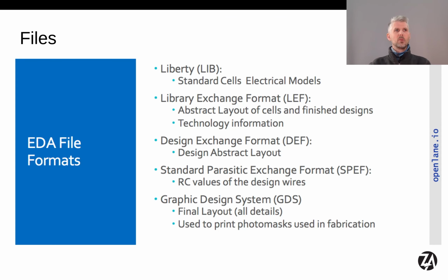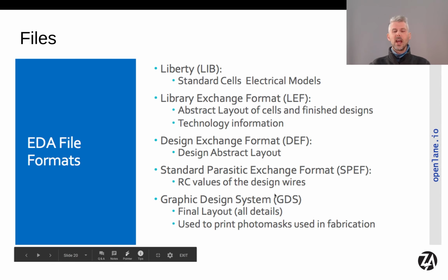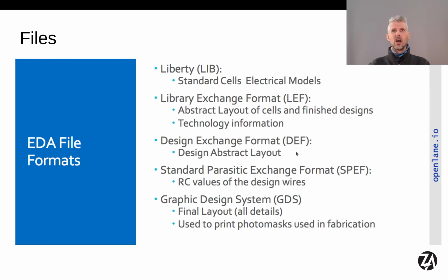So a quick note about files. The most important ones are the GDS files. Those are the ones that we end up generating and sending to the factory. And then we'll be working a bit with DEF and LEF files. So once you have millions of cells in your design, loading up all of them and all their internal detail is a real struggle for your computer, even if it's a powerful one. So we have this abstracted view, and that's a DEF file. So you'll get where things are and where the inputs and outputs are, but not information about what's actually inside them. And if you want the information about what's inside all those cells, then you also have to load the equivalent LEF file.